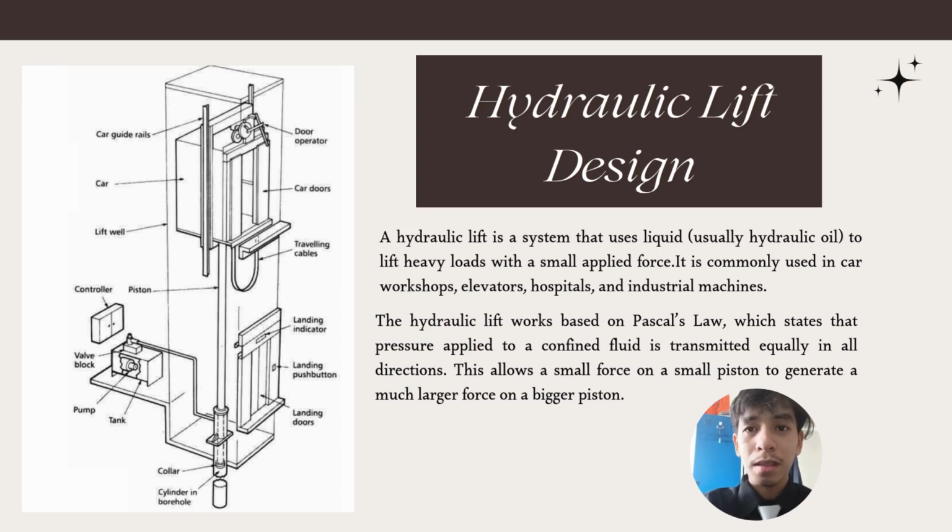Other than that, the hydraulic lift works based on Pascal's law, which states that pressure applied to a confined fluid is transmitted equally in all directions. This allows a small force on a small piston to generate a much larger force on a big piston.